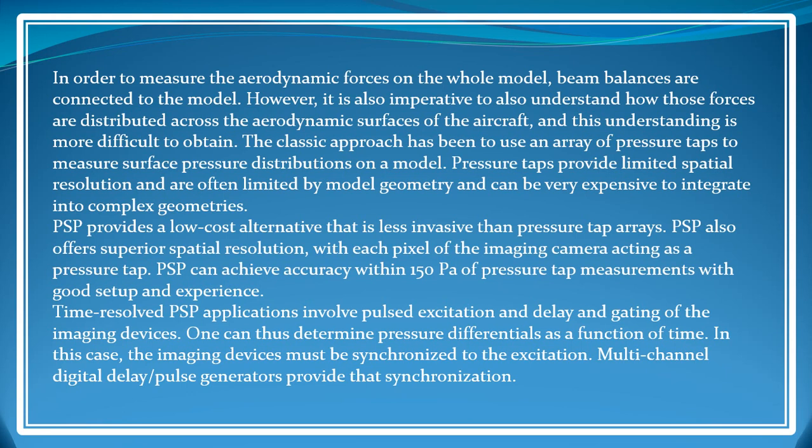We are getting an image output. We can capture it with pressure sensitive cameras that we use in the aerodynamics field. We can capture the image and make an output, so we can treat every single pixel as a pressure tap. So it's giving a very accurate output at less cost, and we don't need to make an array or any complex assembly, so we can easily make it and it takes less time, so it's very good.